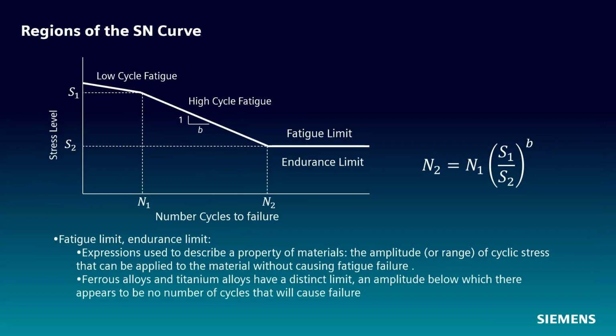All right. So the first thing we need to understand when we're starting this fatigue damage calculation is this curve here. And this is called an SN curve, or a Wöhler curve, named after Herr Wöhler, a German fellow who did a lot of initial research into these failure issues that we have, particularly with trains at the time. But we've taken that and applied it to many different materials.